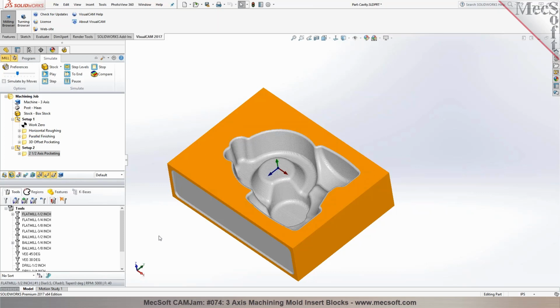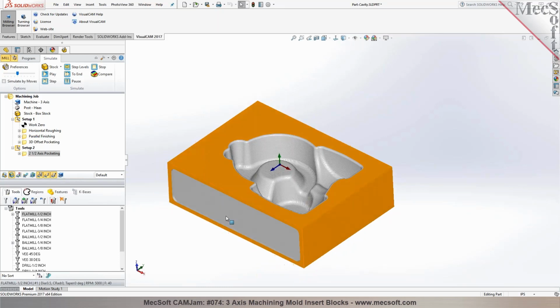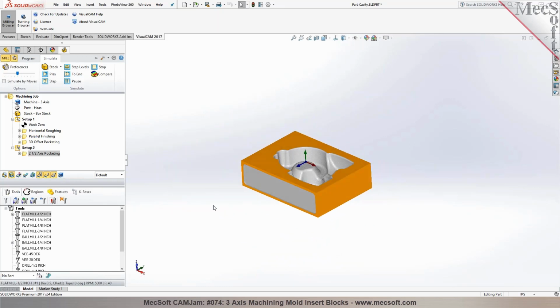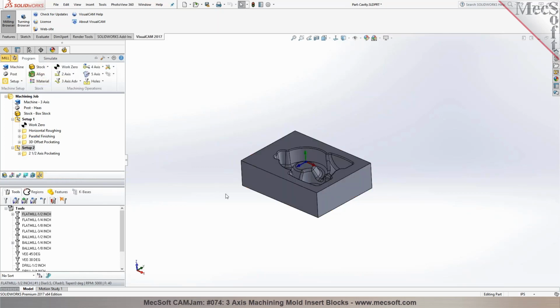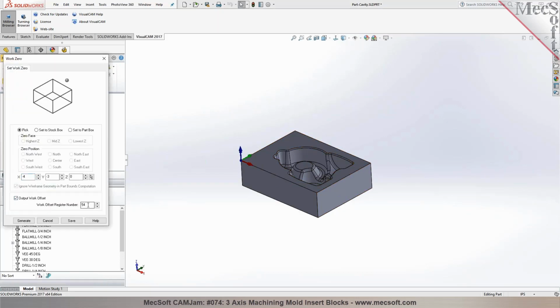Okay, yeah. But let's say we envision having 3 clamps side by side, maybe, and rotating the part from the top to the left to another face with a different G-code for each position. So can you visualize that too with Visual CAM? Yeah, so what we do here is just output the work offset number. So for example, for the machining of the top features in the part, you could be using a G54.